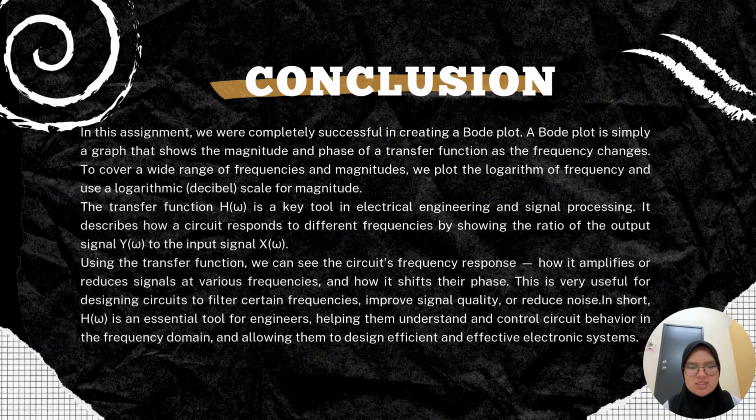For conclusion, in this assignment, we were successful in creating Bode plots. A Bode plot is simply a graph that shows the magnitude and phase of a transfer function as the frequency changes. To cover a wide range of frequencies and magnitudes, we plot the logarithm of frequency and use a logarithmic or decibel scale for magnitude.